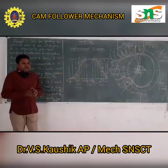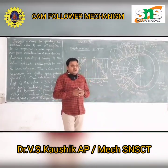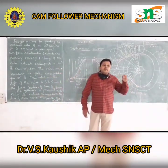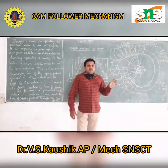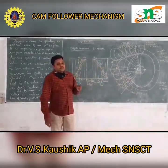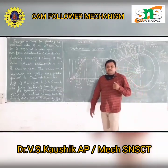In an IC engine, there are two valves. One is the inlet valve, the other one is the outlet valve. We are using the cam mechanisms for opening and closing the valve, or opening and shutting off valves. Those mechanisms are followed by either roller follower or knife edge follower or flat surface follower due to the requirements and their usages.